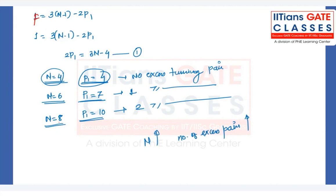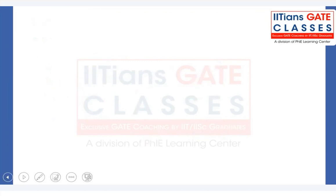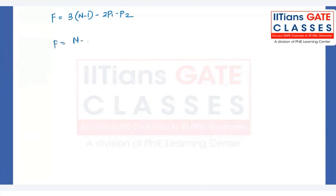So the basic formula, I'll repeat. Degrees of freedom can be calculated using the general formula 3 times (n minus 1) minus 2 times P1 minus P2. Okay. That is also n minus (2l plus 1), and the number of pairs can also be calculated by n plus l minus 1. Okay, so these are the formulas which we should know.